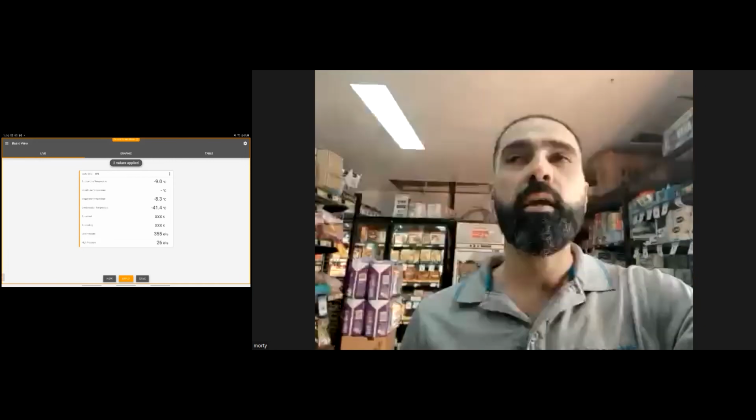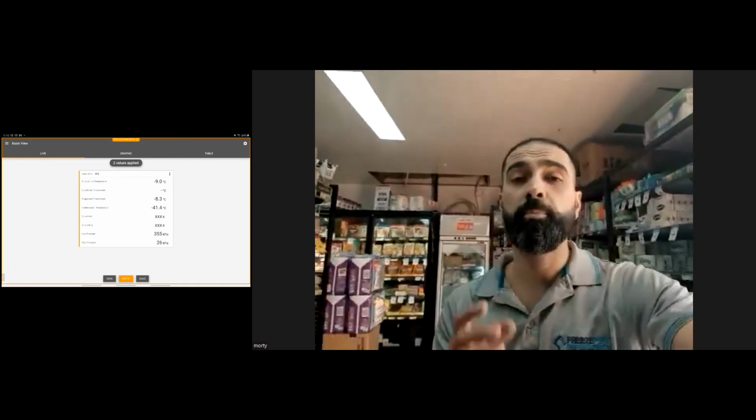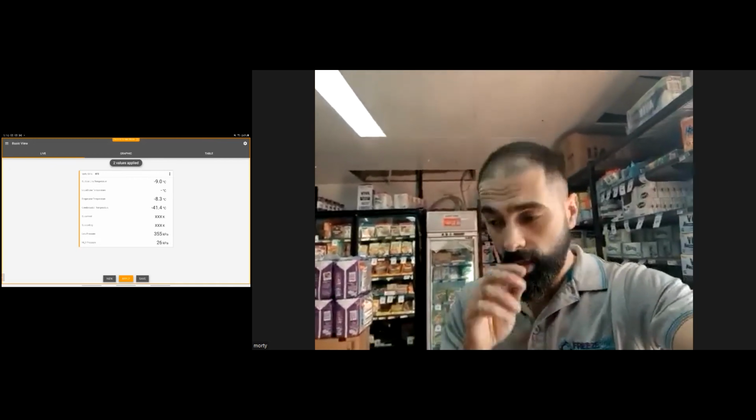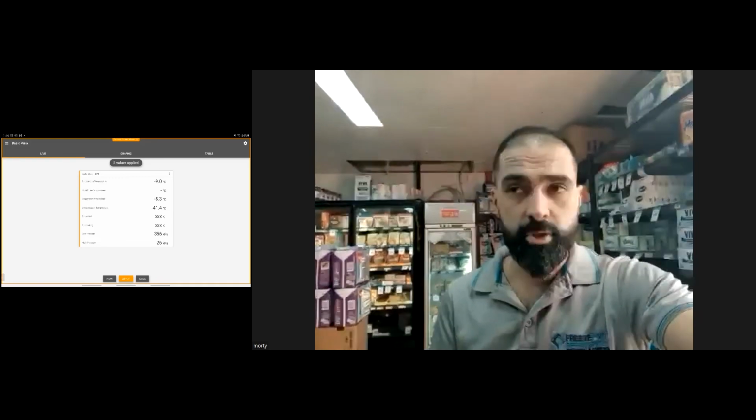It all depends. It's actually a good question. A lot of people ask me a similar question like this. It all depends on the application. So if you've got fruit and veg that requires high humidity, you will need to run it at a lower TD to keep the humidity in the room. So lower TD helps the system, the room superheat, the room ambient temperature low, and also at the same time keeps relative humidity in the room.